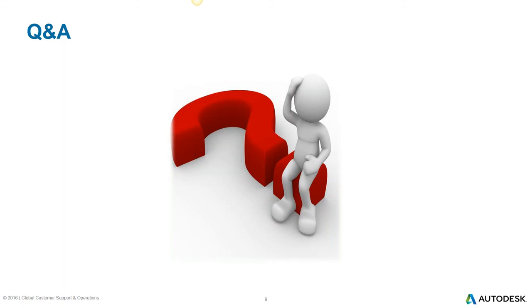Okay. So can leader tips be made so they automatically change size according to the scale of drawing? So that's basically what we're talking about with annotation styles. So standard is just whatever size you specify. Annotative will work based on your drawing scale or your viewport scale.